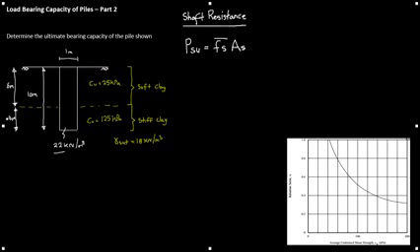So moving on to shaft resistance, PSU equals FS bar AS, as before, FS bar being the average ultimate side resistance per unit area, AS equaling the surface area of the pile shaft in contact with the soil, but as I said, it works slightly different for clayey soils. Now you may have seen the equation before, FS bar equaling this equation here, and obviously it is to do with integration because we have this symbol here that we should all be familiar with.